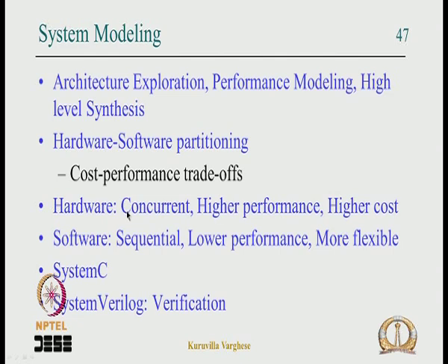So it will be good to have a system modeling language where we can model it together in one language, work out the cost performance trade-off and freeze it, then go for the hardware design and software design after partitioning. Languages like SystemC allow system modeling, and there is SystemVerilog, which is mainly used for system verification. So that is all about system modeling.